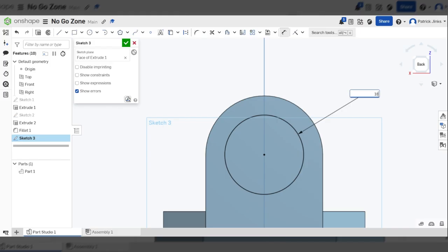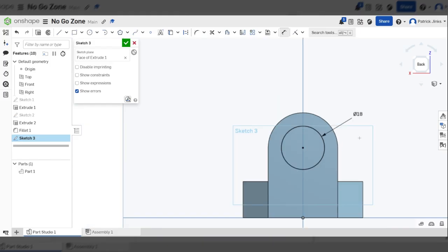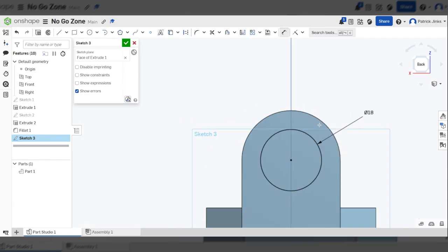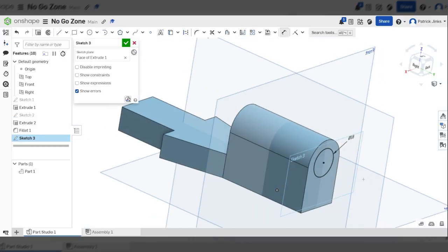of a CO2 capsule. You might be wondering why we're dimensioning the circle at 18, whereas the bigger radius was 13. That's because OnShape measures fillets by radius, so that's halfway across the circle. And it measures full circles by diameter. That's the full way across the circle. So if you imagine this arc here, that's got a diameter of 29, but a radius of, I think it works out as 13.5. And now what we're going to do is an extrude remove.